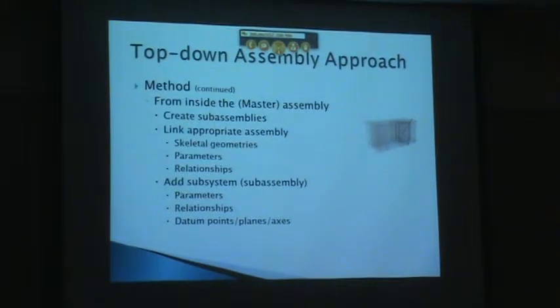And you add additional parameters that are going to define kind of the diameter of the wheel, the width of the wheel. You're going to add parameters that control the things that are very specific to that, not so much where it's located. So it's going to get where it's located and some basic size information from up here, the assembly. It's going to pull that down, but it's going to have additional knowledge that you have to put into it to make it robust and updatable.